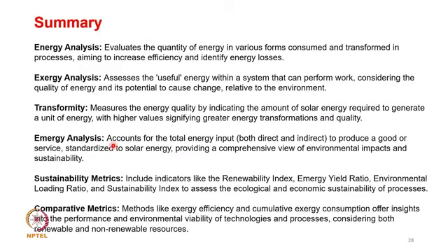Okay, so I think we are now concluding our discussion today. We will just summarize what we have learned. So what is energy analysis? It evaluates the quantity of the energy in various forms consumed and transformed in a process, aiming to increase the efficiency and reduce energy losses. Exergy analysis assesses the useful energy within the system that can perform work, considering the quality of energy and its potential to cause a change, but relative to the environment as the environmental state.